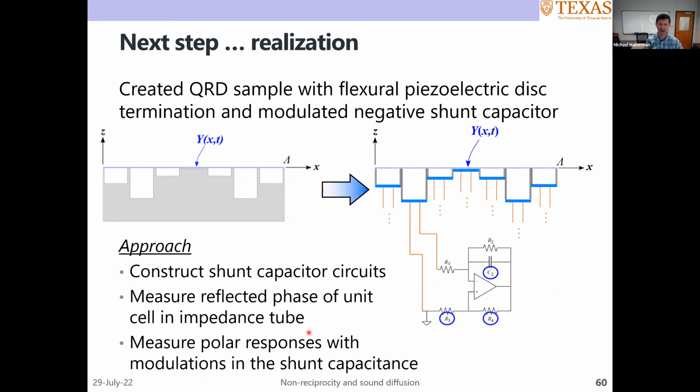It sounds fine, meaning we don't hear anything. We see some electrical noise, but not any mechanical noise or audible acoustic noise. So it is literally just changing the input impedance, and it's doing so via this shunting circuit, which is basically a very high input impedance op-amp circuit. It's like changing the impedance on a microphone preamplifier board, if you are familiar.